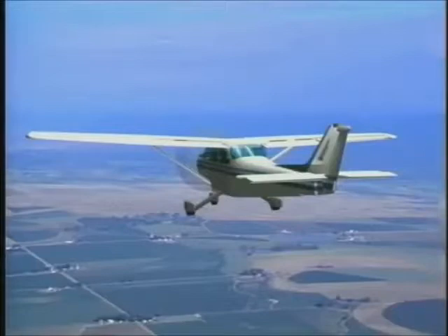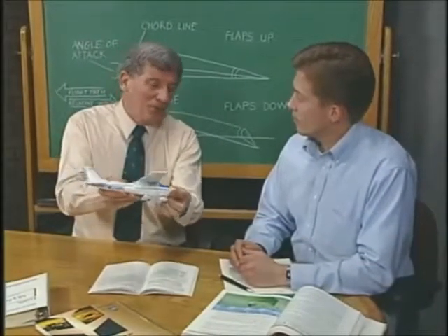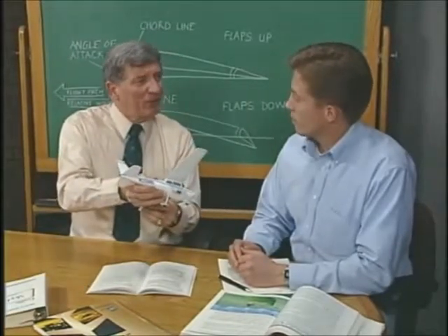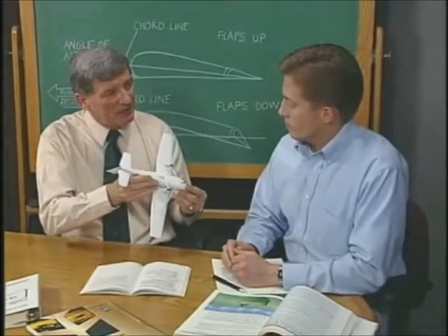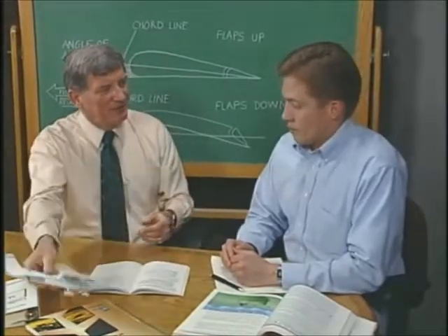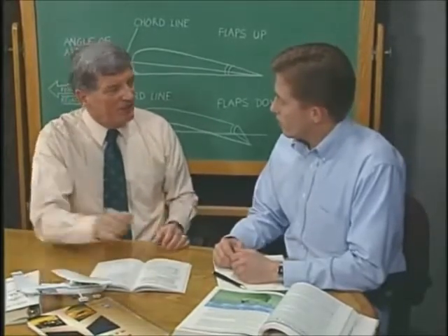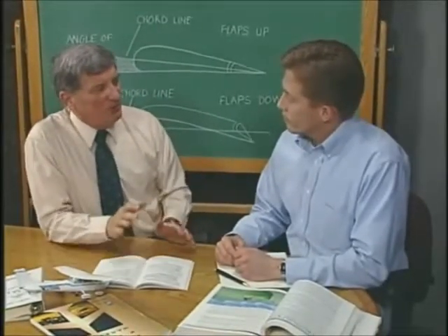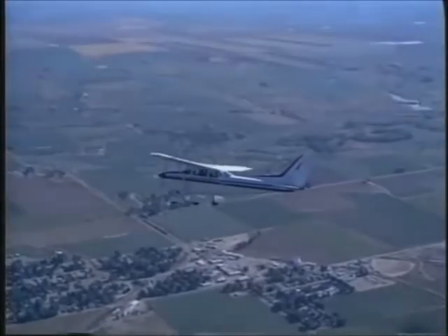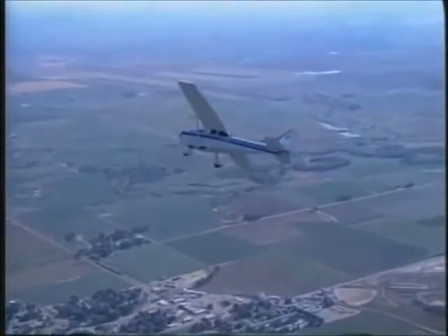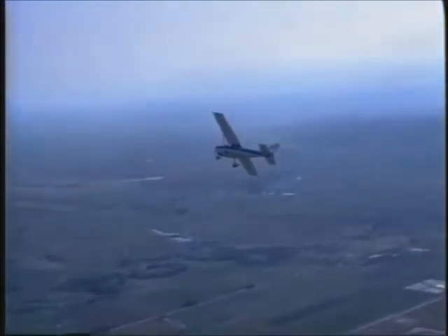In a crossed control stall, the airplane may stall with little or no warning. The nose may pitch down and the inside wing suddenly drop. The airplane may continue to roll into an inverted attitude. This is usually the beginning of a spin and can be very dangerous at lower altitudes. Early recognition of the characteristics of a crossed control stall is very important because recovery may be impossible due to the altitude needed for a safe recovery.